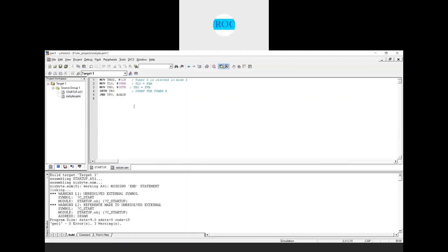something like again here. Again the same instruction; it has to keep on monitoring this bit till the timer resets to 00, till the overflow flag is set to 1. It has to keep monitoring that. Once the overflow flag is set, now you stop the timer. For that, CLR TR0, right?